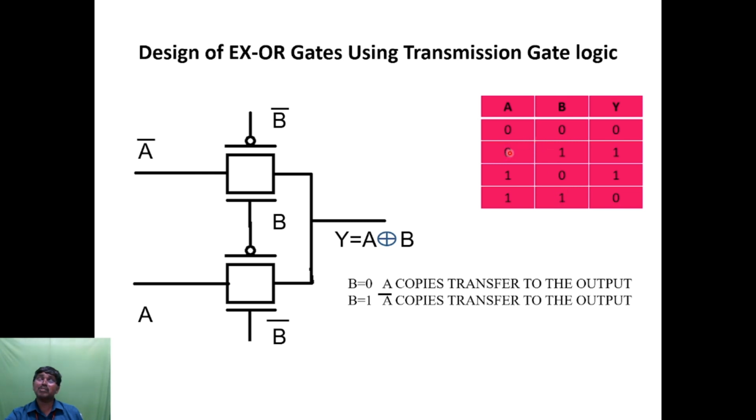When data input is equal to 0, the output is equal to 1. Now when data input is equal to 1, the output will be 0. Now what does it mean actually? When the control input is high, whatever the data input is, the output will be just the opposite, meaning inverted. That means 0 will be inverted to 1, and 1 will be inverted to 0. So that is the concept behind this.